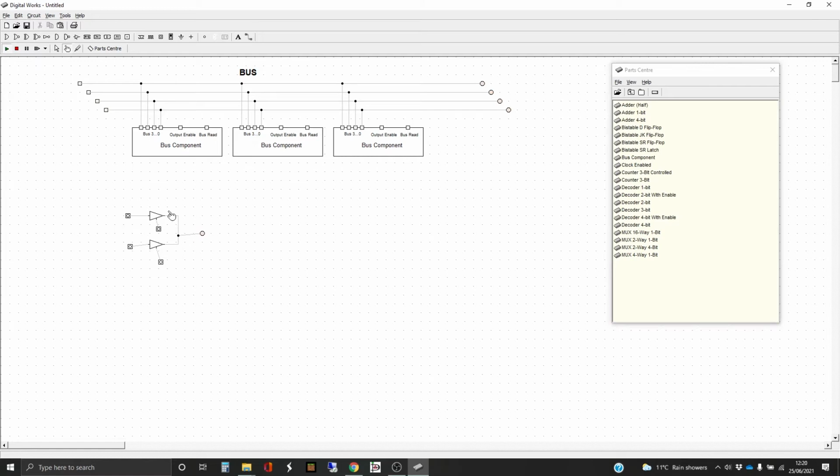It's in an indeterminate state because nothing is actually telling it what value it should have. And if we use the logic probe, which we haven't used very often before, you can see that the grey here, as we click on it, means 0 because these wires are 0, but this one doesn't have a value. It's indeterminate. Let's go back to the hand.